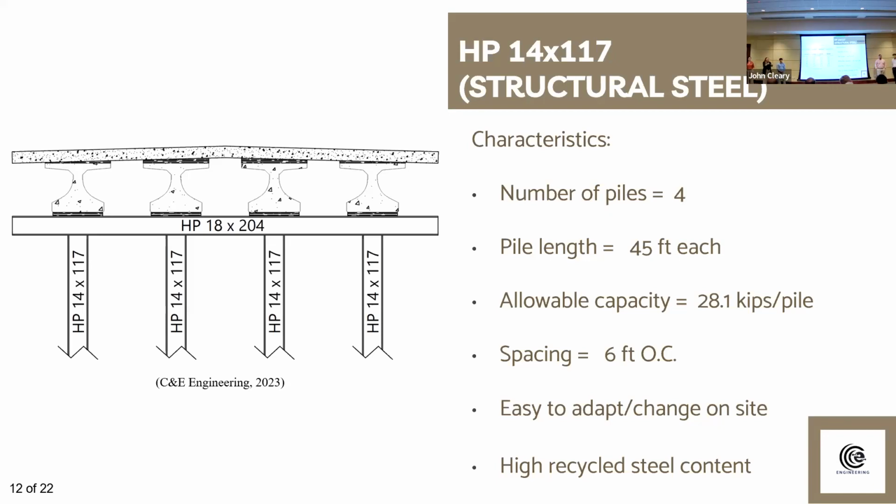So your fill material, you said that was gonna be a sandy clay. Did y'all take into account any bedding material or some sort of filter fabric to make sure that doesn't wash out? Yes, in our cost estimate, all fill material, the gravel for the road tie-in, and the concrete tie-ins all have that fabric material included.